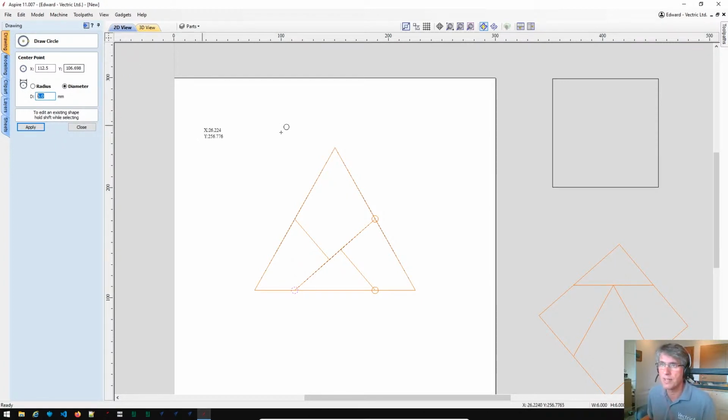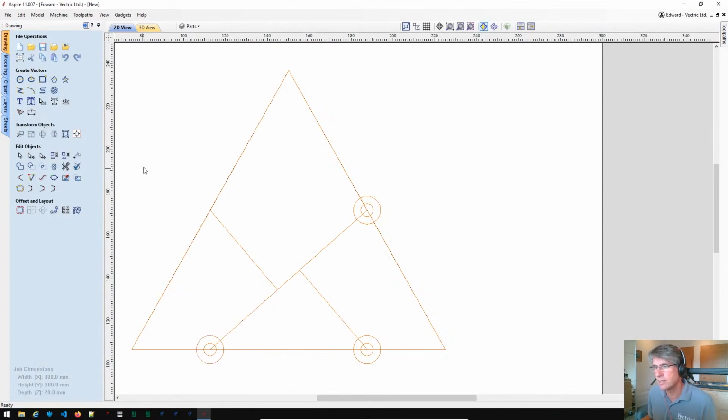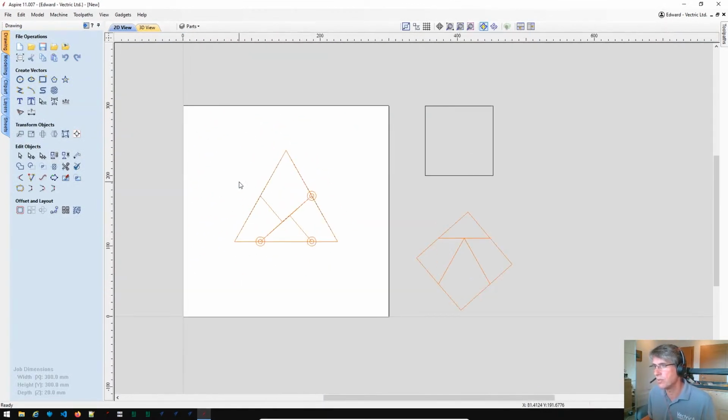So what I'm going to do is add an additional radius around here, which is just 4 millimeters off here. So in total that will be 13. That's given me a 4 millimeter gap between the inner and outer of our hinges. And really that is the geometry that I'm going to use to make this part.